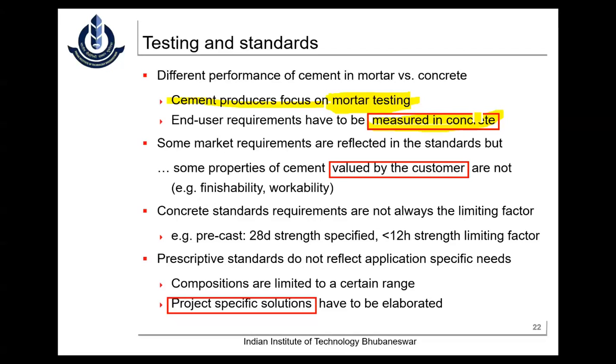Many of the small contractors never do that. They don't have a proper compression testing machine. They simply rely everything on the cement manufacturer. Whatever cement they give, they mix it and supply the concrete. If some problem comes, you have to revert, and then we go and do the post-mortem. So we need to look at this in a very broader perspective. That is what I want to emphasize.